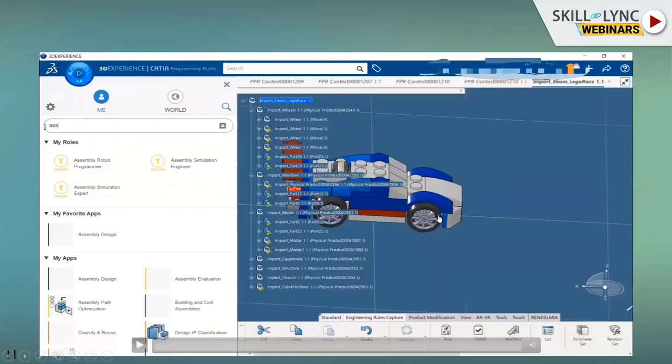So once you have the cylinder, you can make it like a wheel and do your design. You have those standard options like extrude, or create a pocket, or create a hole, or chamfer the edges, or fillet the edges, etc., or smoothen the edges, and so on. So you have a lot of different steps, and then you end up with different parts, like wheel, or axle, or different parts that you will be able to create. And then you bring those parts together to form your assemblies.